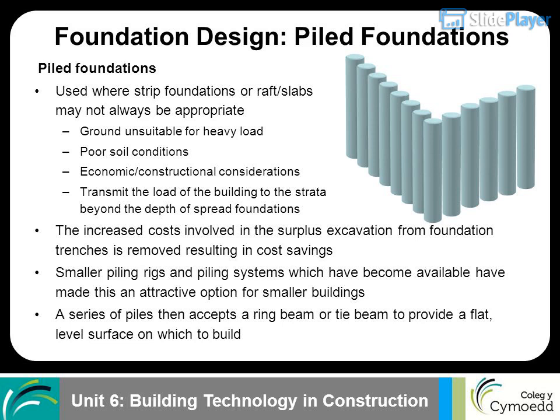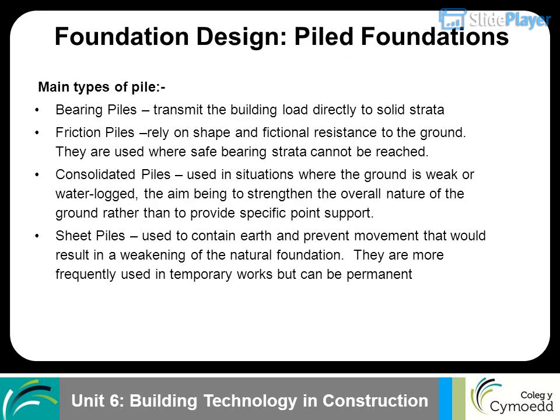The increased costs involved in the surplus excavation from foundation trenches are removed, resulting in cost savings. Smaller piling rigs and piling systems which have become available have made this an attractive option for smaller buildings. A series of piles then accepts a ring beam or tie beam to provide a flat, level surface on which to build.